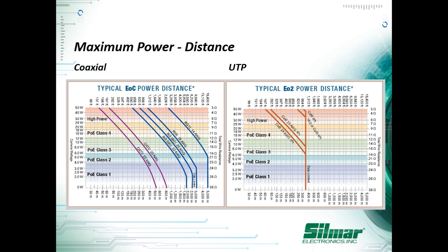With coax, which is RG59 or RG6, we sell a transmitter and receiver that allows you to transmit not only power, but data as well across up to 3,000 feet of coax. And I'm not talking about Siamese cable. I'm talking about literally only using the coax, the RG59, to transmit both the power and data across up to the 3,000 feet. And I keep on reiterating "up to" because there is a little bit of a max, and we'll go over what the maxes are in a second.